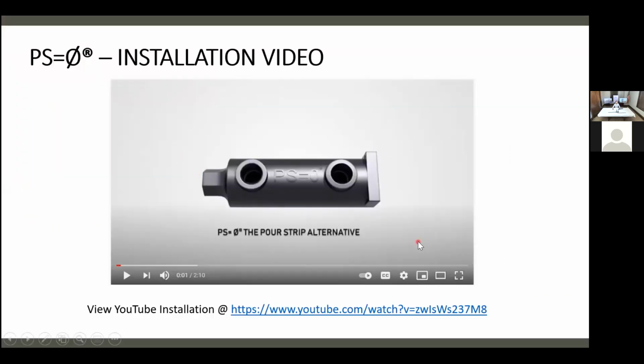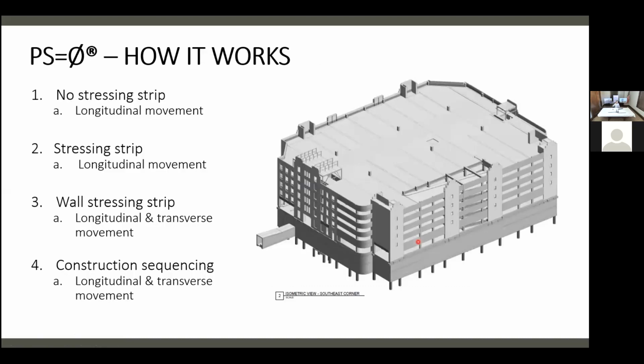So again, that was our typical application where you have a slab to slab, but you notice in that second slab pour, you have to have access to the outside of that second slab to stress if it's PT.